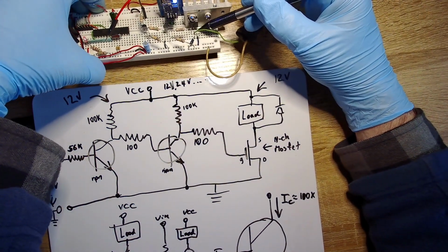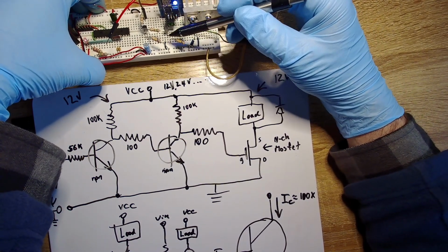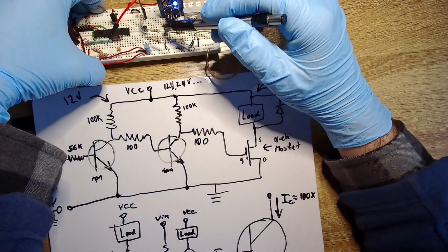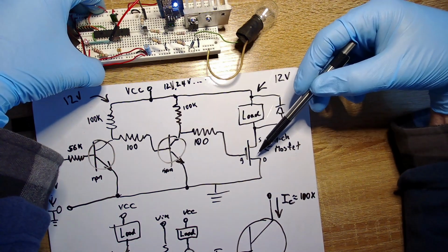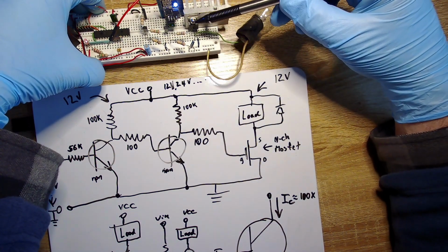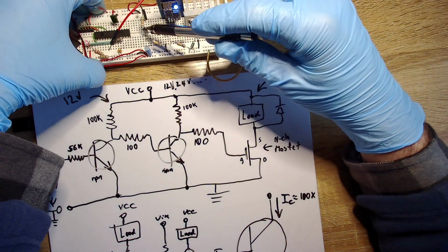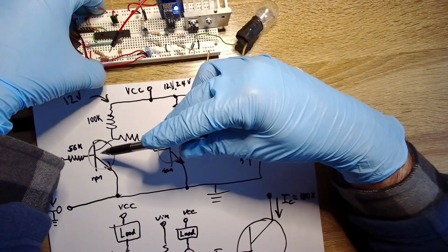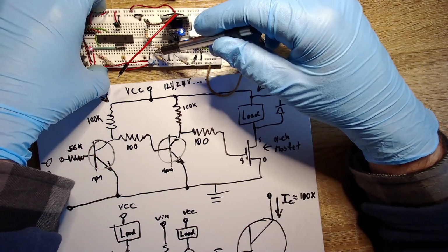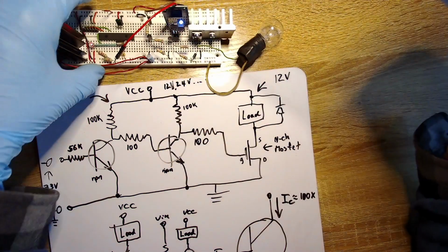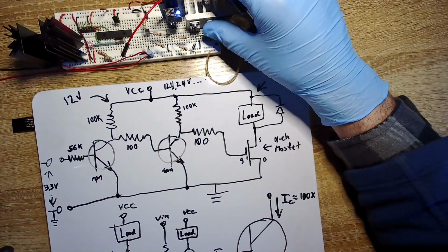So this pin, obviously, is connected to ground. This transistor also, its emitter, these are NPN transistors, by the way, as noted here. And this is a MOSFET, an N-channel enhancement mode MOSFET, right here. And this first NPN transistor also has a pin, if you can see behind here, grounded. So the circuit that we see on the diagram is exactly what's on the board here.